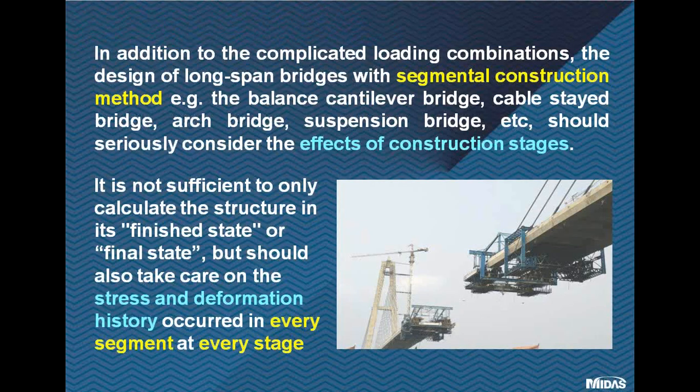In addition to the complicated loading combinations, the design of long-span bridges with segmental construction method, for example, the balanced cantilever bridge, cable stayed bridge, arch bridge, suspension bridge, etc., should seriously consider the effects of construction stages. It is not sufficient to only calculate the structure in its finished state or final state, but should also take care on the stress and deformation history occurred in every segment at every stage.